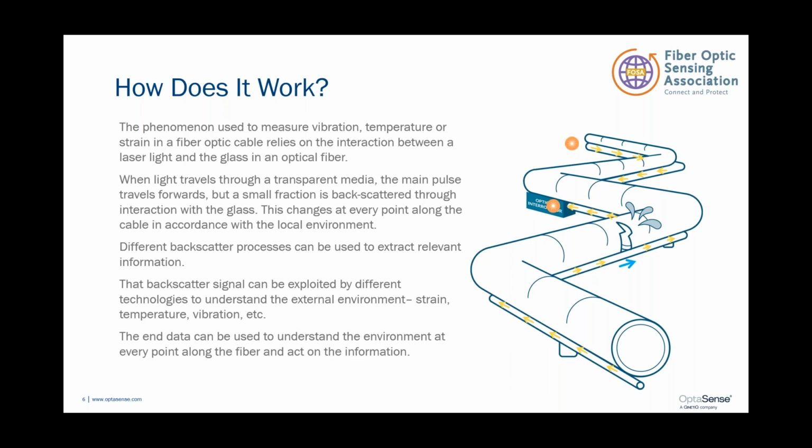At the low frequencies, we can pick up strain and temperature information. At the higher frequencies, it's vibrations and acoustics. And with an engine that looks at the evidence of each of these measurands in each sampling point along the fiber, many thousands of them all at the same time in real time, we can look for the evidence of a leak.